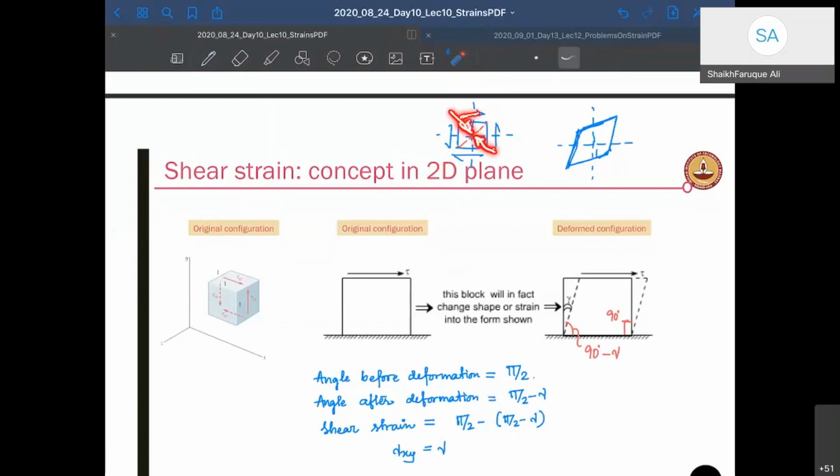So if you draw the Mohr circle, you will see if you have an element in this direction, a 45-degree angle element, you will see that this one is acting and there is a compressive force that is acting here. Do that and see. So therefore this point will try to move inside, this point will also try to move inside, both of them, but this point is trying to go out and this point will try to go out, and therefore it will look like this. So this has moved in, therefore this diagonal will squeeze, whereas this diagonal will elongate. Okay, and it will make an angle here. So our initial angle here was 90 degrees.